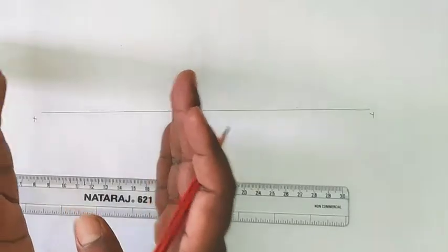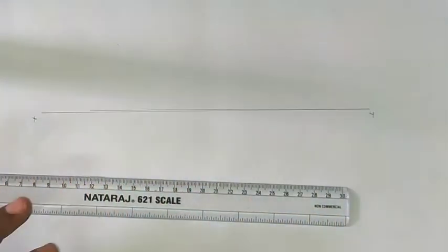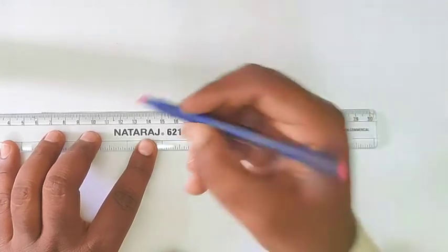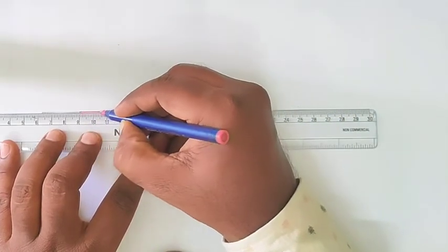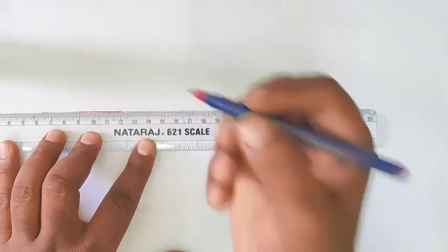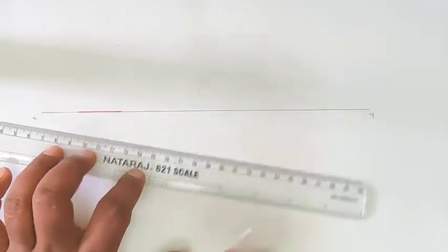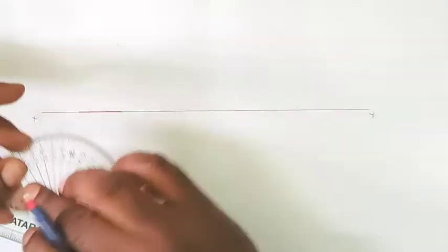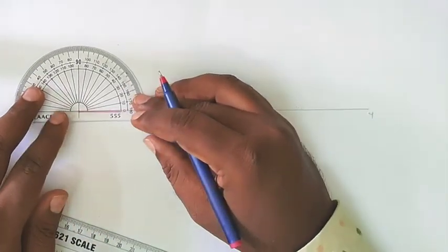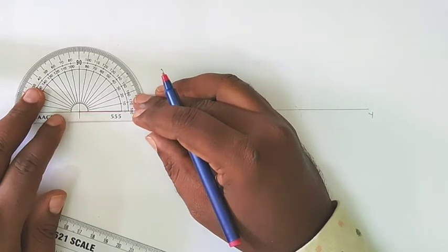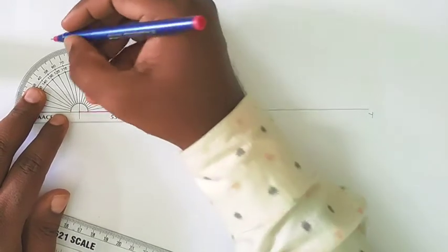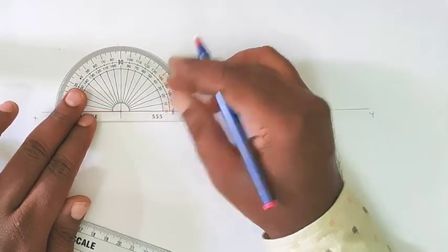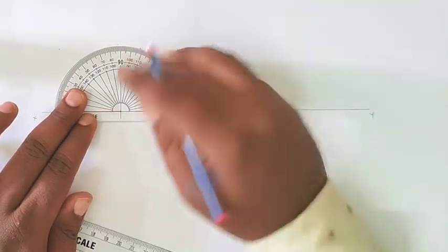So we will draw a side on the reference line as the side view of our diagram. Draw a side on the reference line with 30 mm, a side with 30 mm as the side view. Now we will construct the pentagon, because the side view of that base is a pentagon. By following the exterior angle method, we will construct a pentagon.